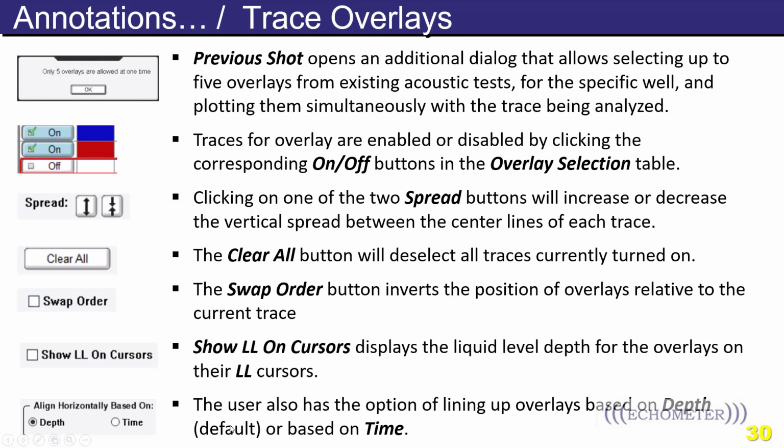And this is important because when you haven't analyzed the well good enough to know the acoustic velocity, if you haven't used any specific method to come up with an acoustic velocity, you better use the time at the beginning to know if you have repeated shots. So you're doing several shots in a day, and you want to see if one specific kick is repeating on those wells.